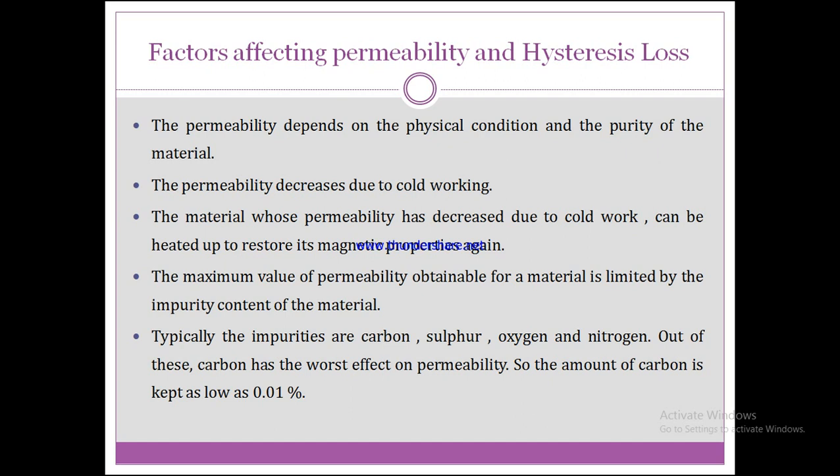As mentioned over here, the permeability depends upon the physical conditions and the purity of the material. The permeability also depends upon the cold working. The material whose permeability has decreased due to cold work can be heated up to restore its magnetic properties again. The maximum value of permeability obtainable for a material is limited by the impurity content of the material.